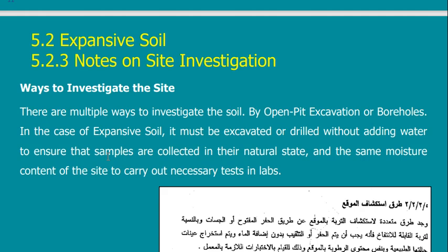But actually the problem is that open pits are very shallow. I can only investigate 2 to 3 meters using open pits. But suppose I have problematic soil at 5 meters or 10 meters, then I will not be able to discover it by this method.